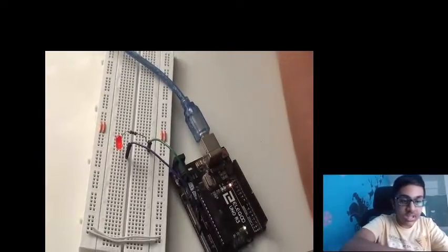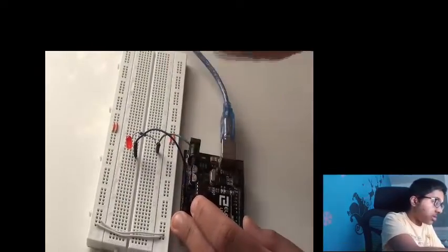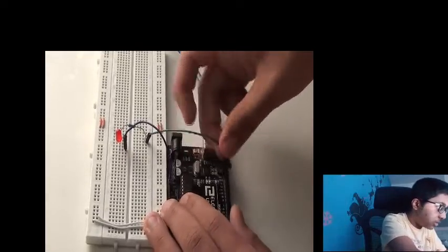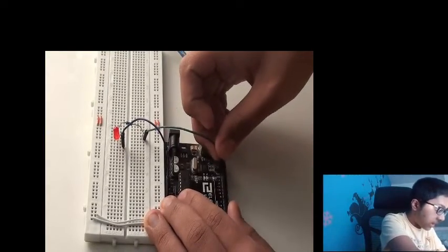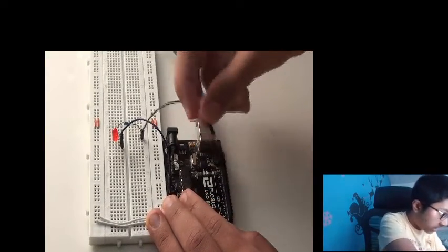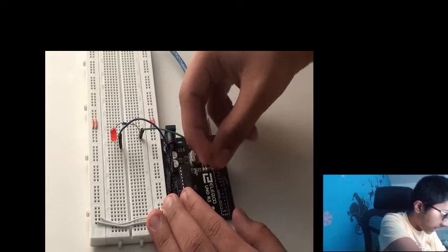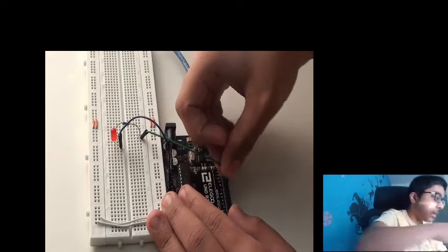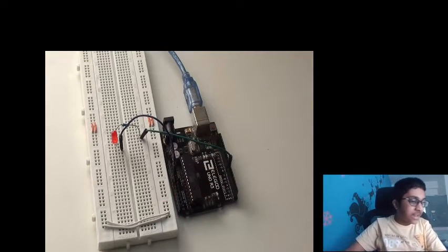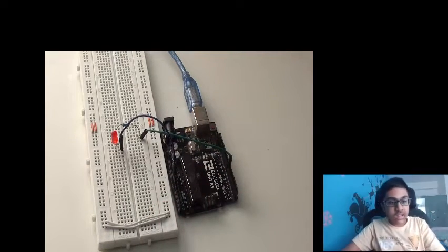Safety first, always disconnect the Arduino and then go into circuitry. All that's going to change is instead of writing a 5 volt directly, we are going to connect it to any one digital pin, anything of your choice, anything from 0 through 13 except 0 and 1. I'll tell you why in a second. Let's connect it to pin 7. And actually that just finishes the circuit.